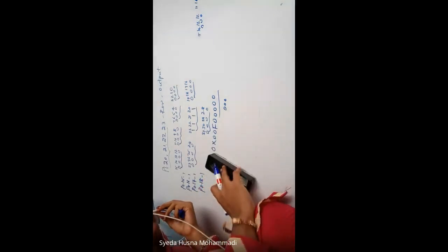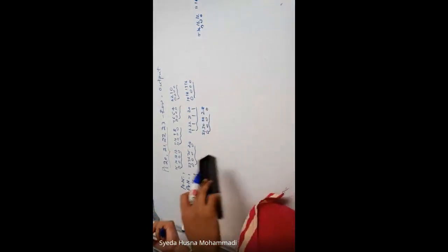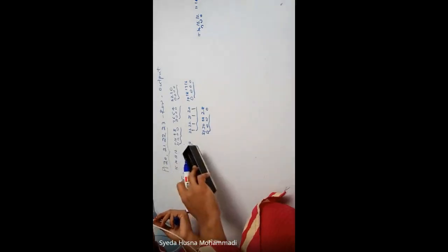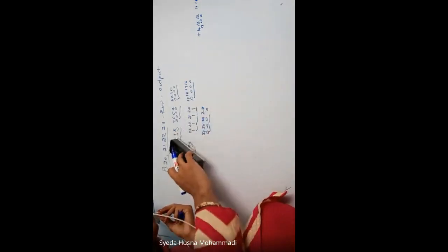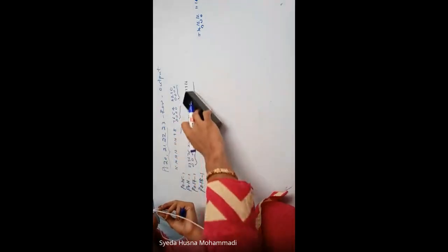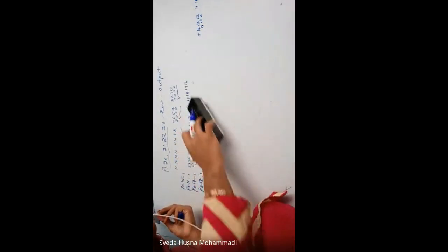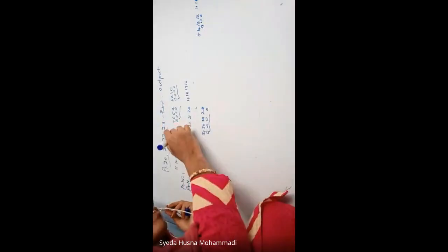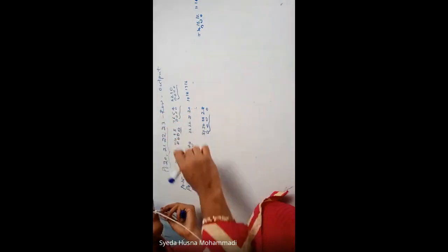If no key is being pressed, the value on all of these will become what? The value on all of these is going to become 1 1 1. If no key is being pressed, the values on all the pins are going to become high because we are not setting any direction. So we have to check whether any key has been pressed or not.